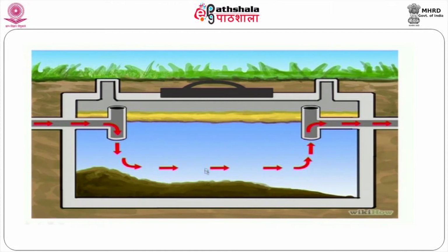The suspended solids will deposit at the bed of the reactor and undergo anaerobic oxidation. In addition, the organic matter present in the feed stream will undergo stabilization. While designing the configuration of the reactor, we have to provide 24 hours hydraulic retention time while considering the volume of the reactor. In addition, desilting is done once in a year or once in 2 years. So, we have to provide enough space to accumulate solids, because the desilting operation is once in a year.